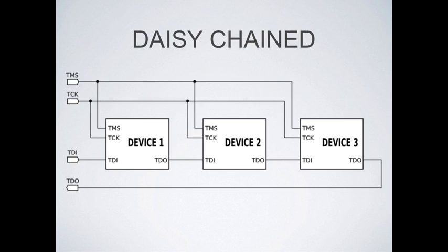Sometimes there are instances where you can't put those devices in bypass mode, and at that time you're going to start to do some more invasive things, where you actually stick 2 wires in between device 1 and device 2, and then stick another wire to get the data off of TDO between device 2 and device 3. It's possible, but then you're getting into a more invasive approach at that point.